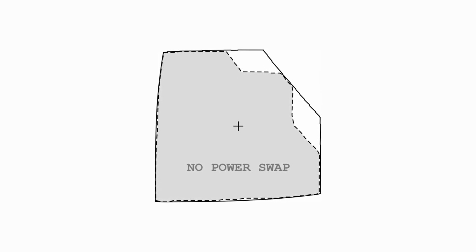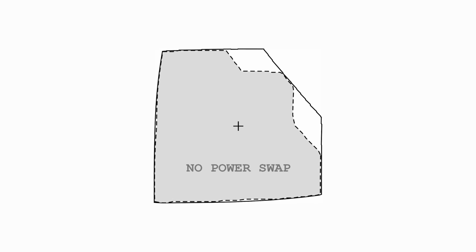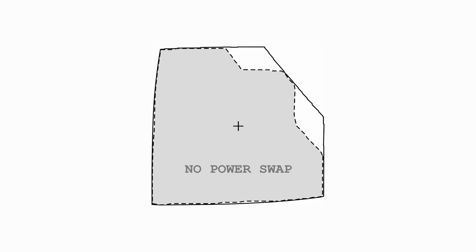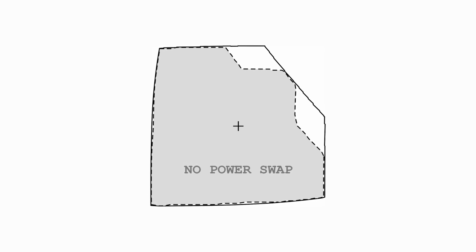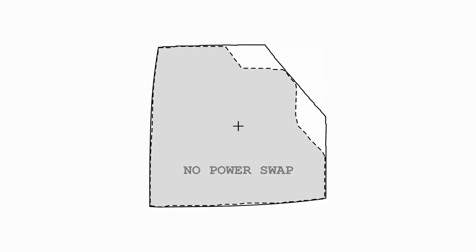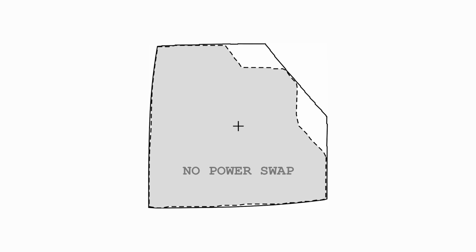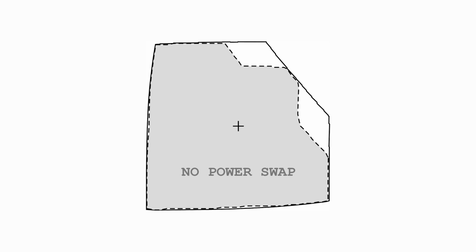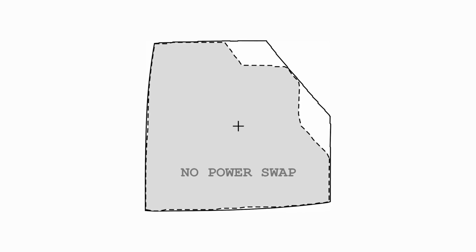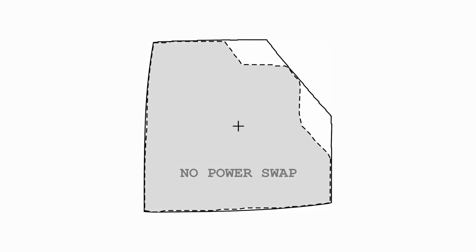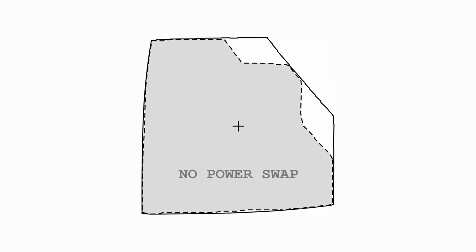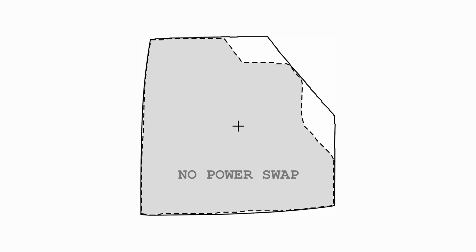And this is an interesting finding of our study, that if we assume perfect network coordination, we get these P-Q flexibility areas, which sometimes look convex. But once we have some coordination issues, or if we assume that this power swap is not possible or not reliable, the aggregated P-Q flexibility areas shrink a lot and they become non-convex. And this poses additional challenges to the operation of distribution networks.